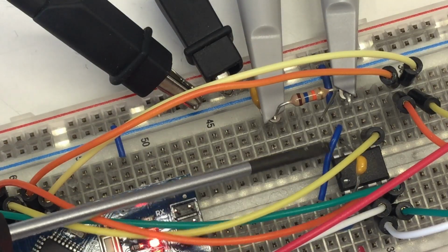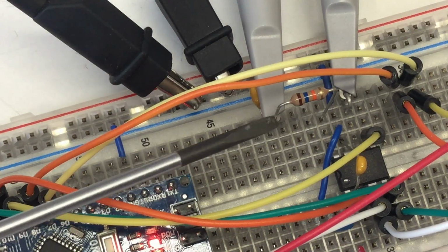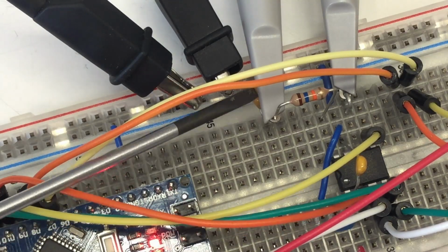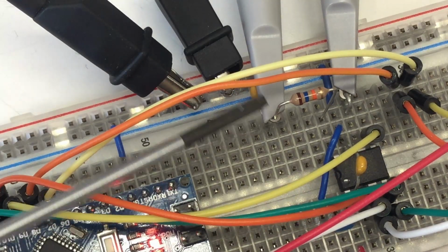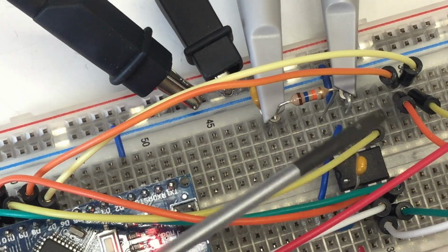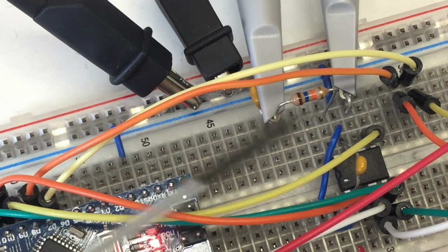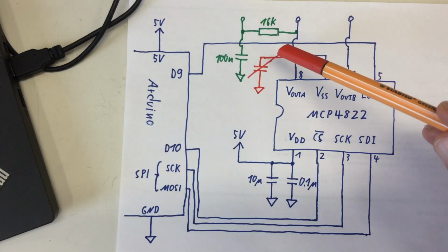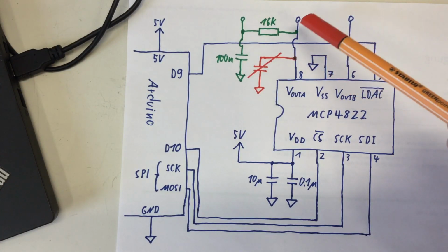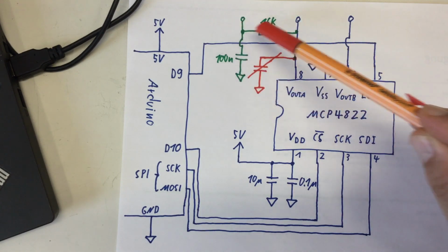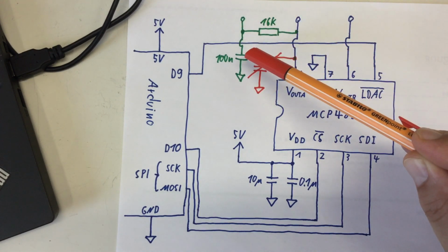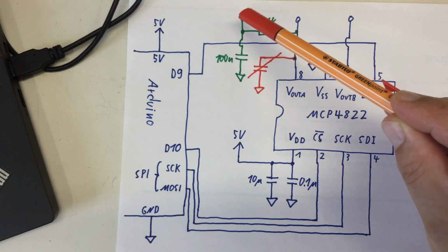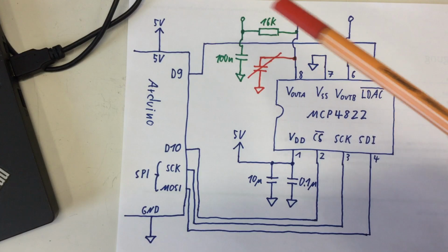Here's my output pin, the resistor, that's my R, I think 16 kilohms, and there's the blob under the oscilloscope probe going to ground, that's my C, 100 nano, and that's an RC filter with a corner frequency of 100 Hertz. And to make things clear in the circuit diagram, I have that RC filter now here, 16K, 100 nano, so a 100 Hertz RC low pass, and my oscilloscope probe is connected here.